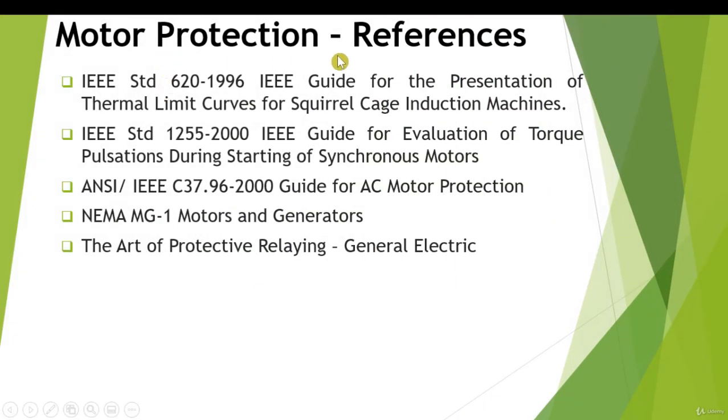So these are the various international references for motor protection. Some of them are IEEE 620, IEEE 1255, ANSI or IEEE C37.96, NEMA MG1 motors and generators, and The Art of Protective Relaying book by General Electric.